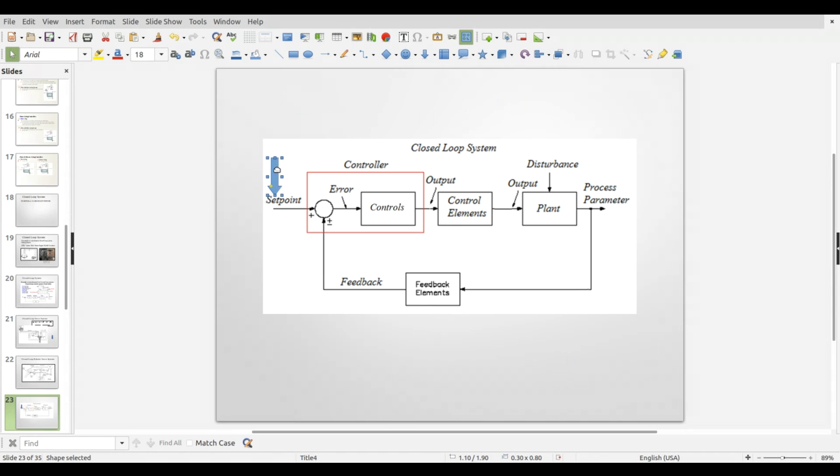And then the operator can change the set point at any time. And so the set point is going to be fed in through our HMI into the controller, the PLC. And of course, we have our sensors, one or more sensors here, converting and feeding that into our analog input. Now our controller is calculating the error, okay?